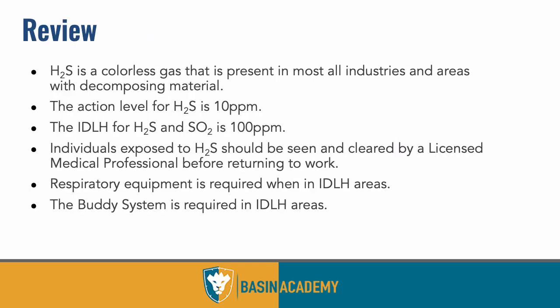So lastly, wrapping this up and summarizing, I try to keep it under an hour. We're just over. But we want to make sure that we understand that H₂S is colorless, highly toxic, also flammable and heavier than air. It's formed when decomposing material happens, or really any time a sulfur element bonds with two hydrogen elements, then you're going to get H₂S. The action level for H₂S is 10 parts per million, meaning that's the point where we need to muster up if we don't have the appropriate PPE.